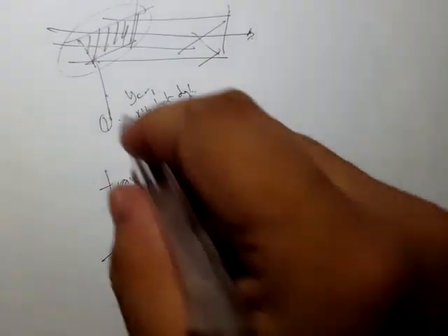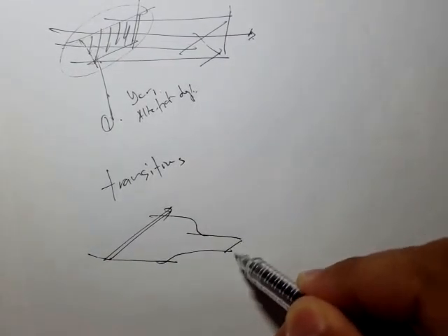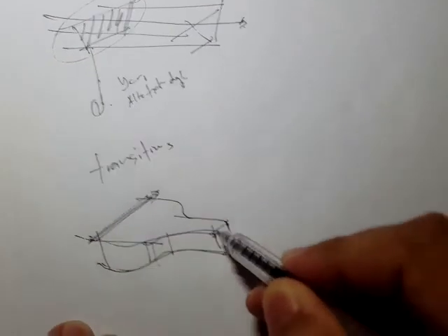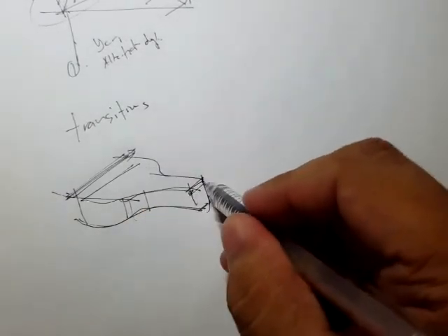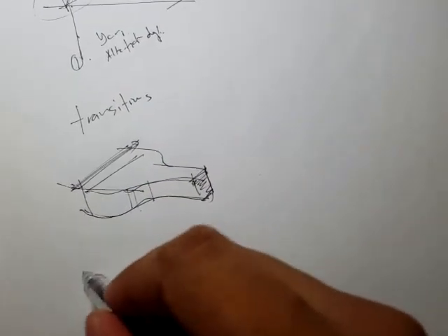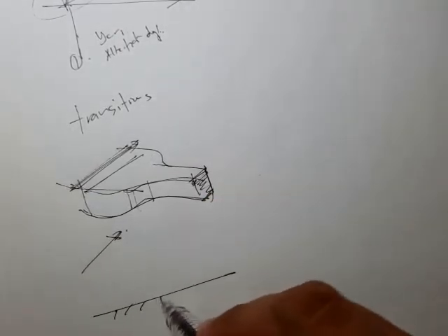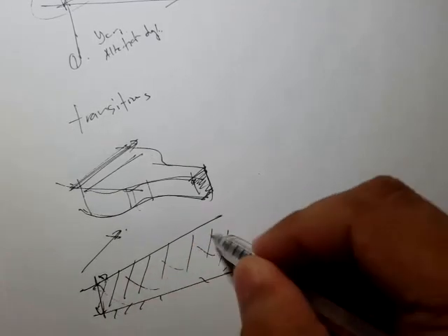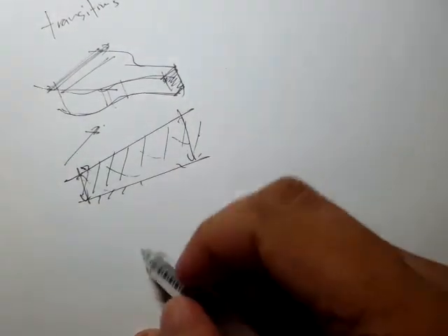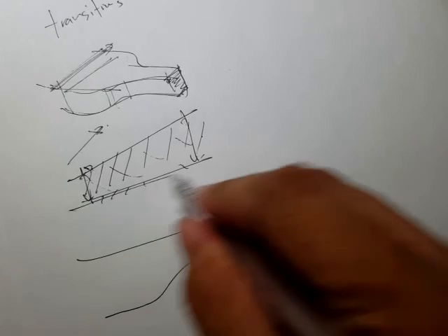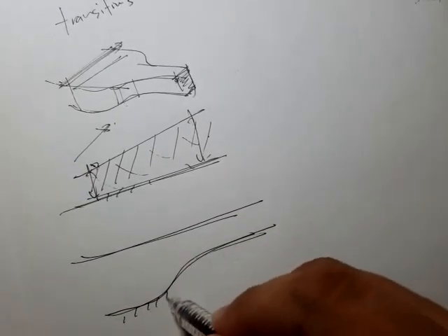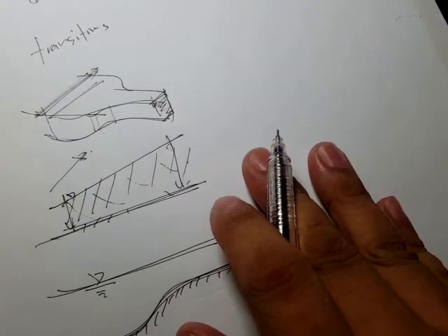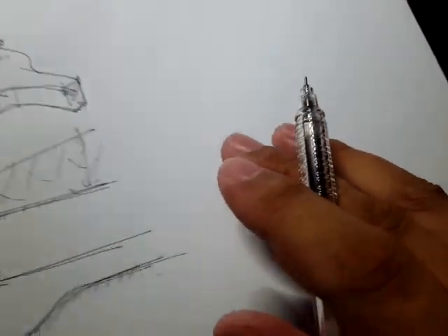So for example, from this width, it goes to this width, say a rectangular channel, but with a transition from a wider width to a narrower width. What's going to be the depth at this end? If we look at this elevation view, what we see is something like this. It can have a non-uniform profile. Here's our flow, here's our depth, and what's going to be the depth right here? The specific energy equation is also used when, instead of a flat bottom, there's going to be a bump, or something that changes the bed elevation. We did not discuss this because of time.